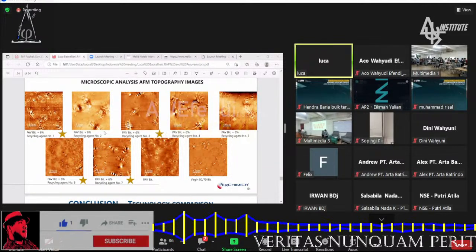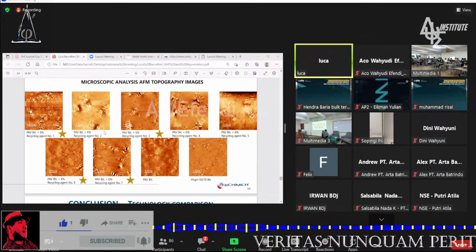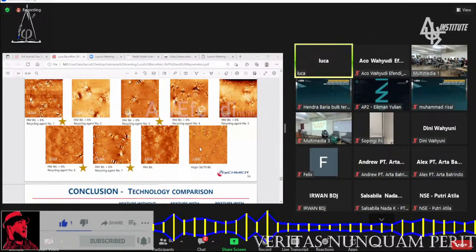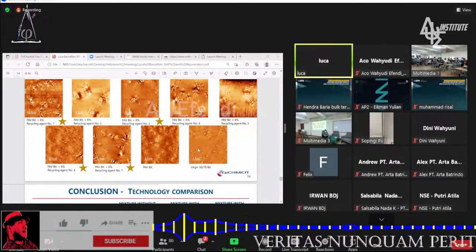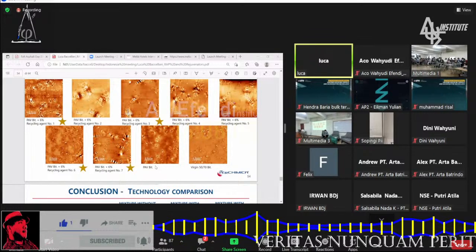Okay, we can put this asphaltene on a heating system and check the melting point of the asphaltene. So what does it mean? If I have a melting point of the asphaltene, not of the bitumen, that is like the softening point, but the melting point of the asphaltene, for example, of a virgin bitumen is 50 degrees. Of the bitumen after PAV is 90 degrees. What happened with flux oil? With a flux oil, I just diluted the asphaltene, so the structure of the asphaltene is the same. So when I do that test, the melting point of the asphaltene is always the same, 90 degrees.